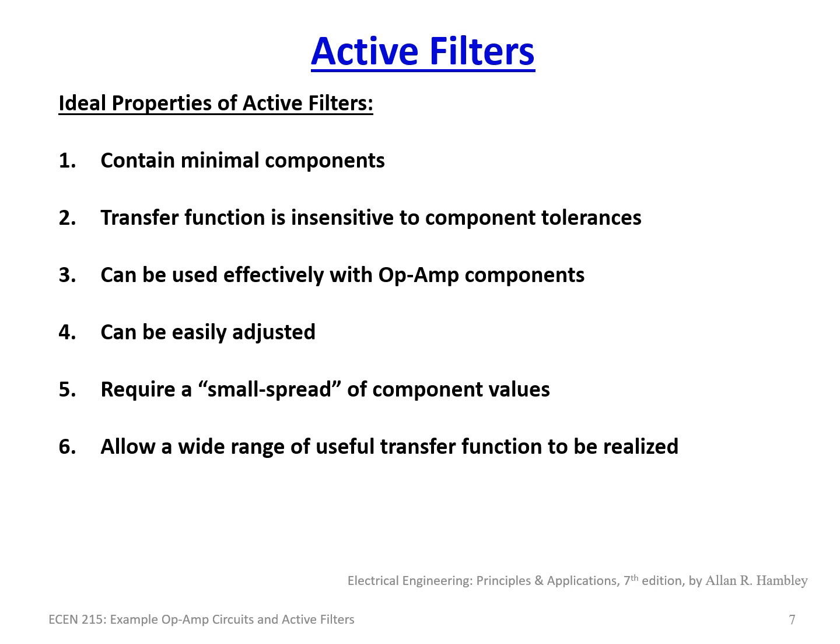And analog control, before we really got into the realm of digital control, was all done with operational amplifiers. So if you were doing a control function to actually control feedback of, say, an actuator or a control valve of some kind on a control plant, you could actually implement this using an active filter and build a transfer function. So once you finally take a controls course in your discipline, which is likely, then you would actually see that active filters can implement those transfer functions that you come up with.